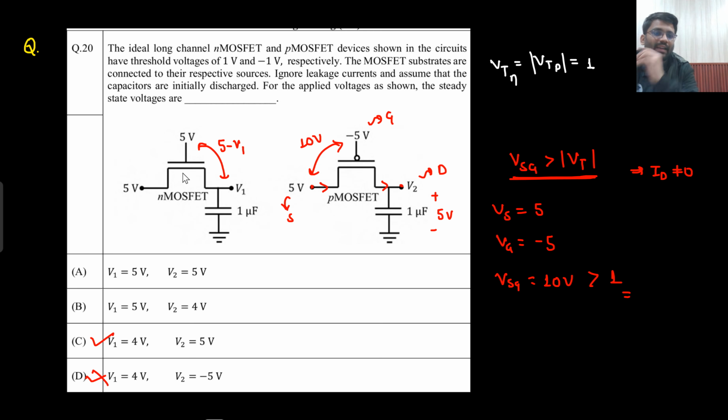But sir, in this case, NMOS, the scenario is that I wanted it to charge up to 5 volt, but what really happened? After 4 volt, it is not able to charge. Why is that so? Because sir, VGS now has become 1 volt. Because of that, the MOS is off. Now it will be able to charge up to 4 volt only. There you go. This is the complete scenario of a pass transistor logic.